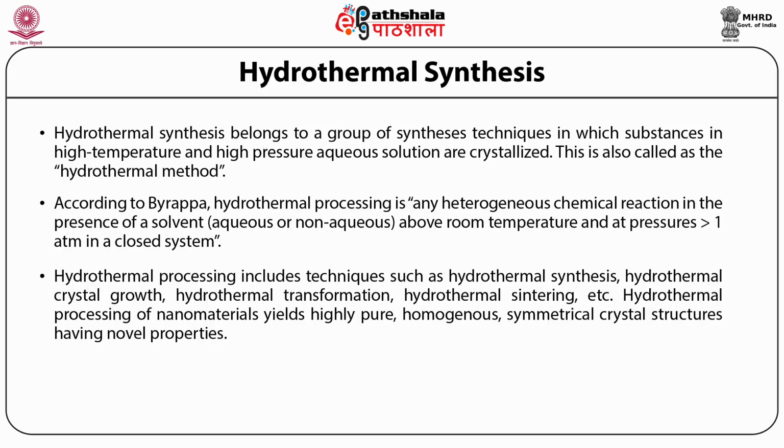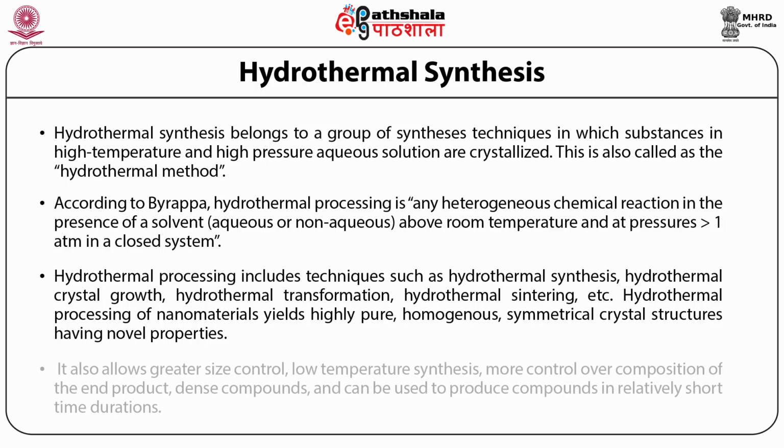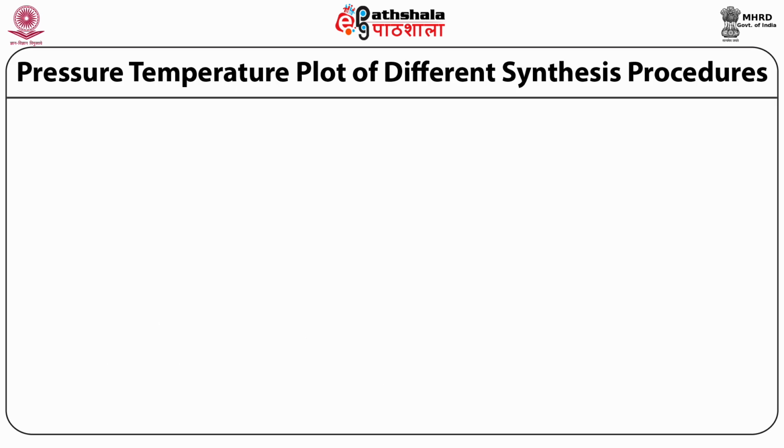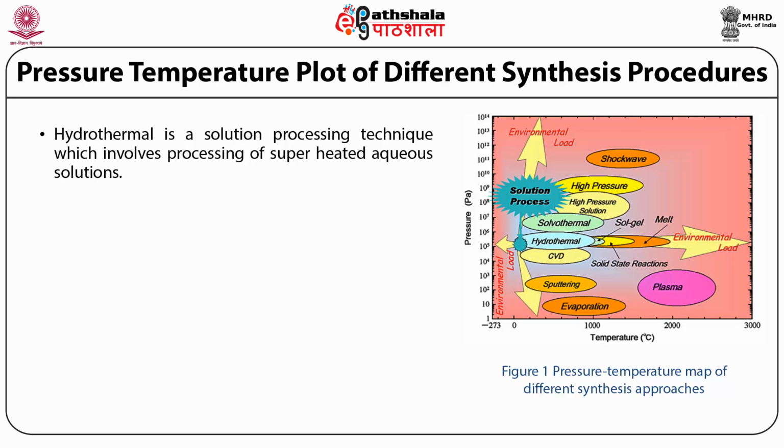Hydrothermal processing of nanomaterials yields highly pure, homogeneous, symmetrical crystal structures having novel properties. It also allows greater size control, low temperature synthesis, more control over composition of the end product, dense compounds, and can be used to produce compounds in relatively short time durations. Hydrothermal is a solution processing technique which involves processing of superheated aqueous solutions.